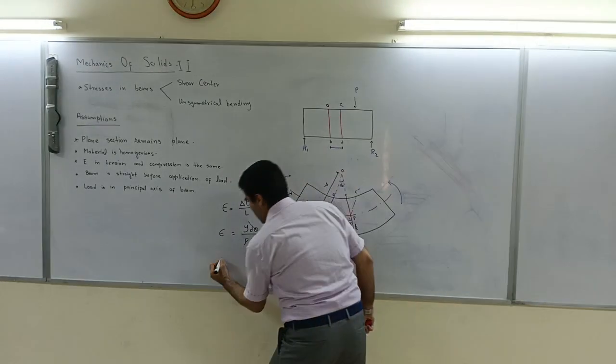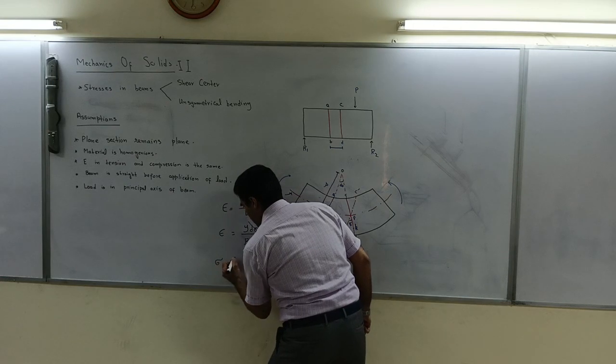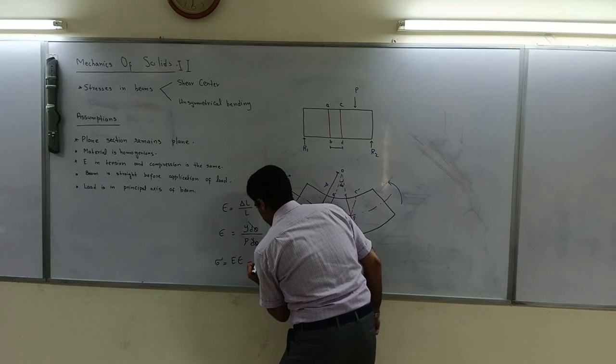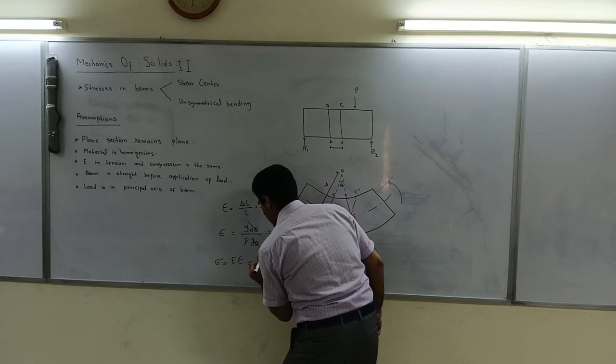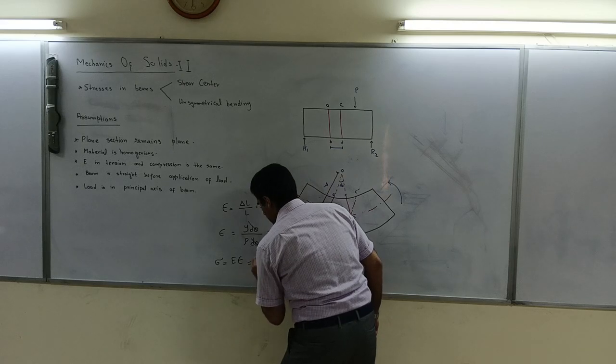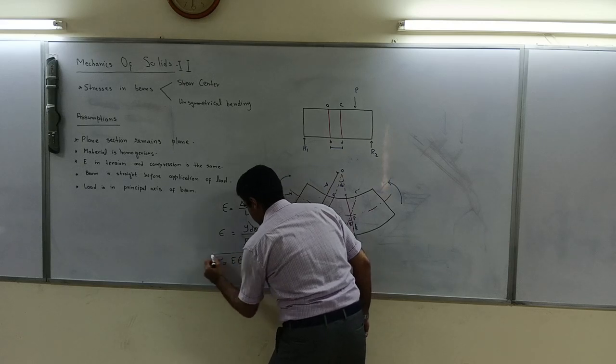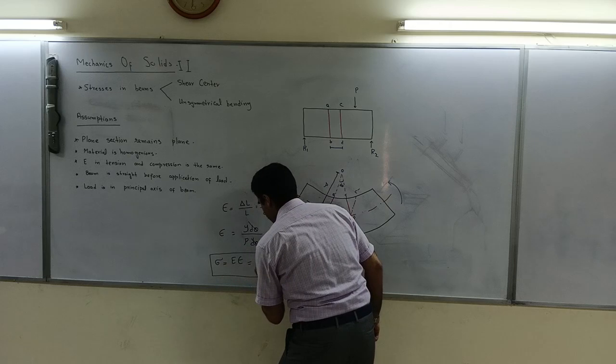Now, stress is equal to E times strain, and this will be E y by rho. That is our flexural stress equation.